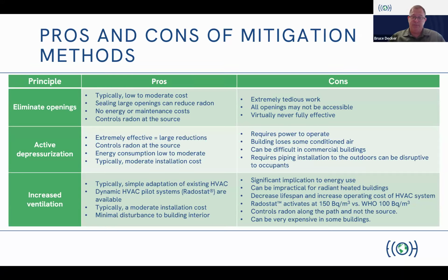There's no energy cost to it, right? You fix it with the building and it controls radon at the source, which is great. But the problem is it's extremely tedious work. Most people don't have the experience to seal the basement or the cracks the way they need to be sealed to be durable and to last. Because you can seal it and the caulking can fail 5 years later and you have a problem again. So you have to maintain this stuff still.